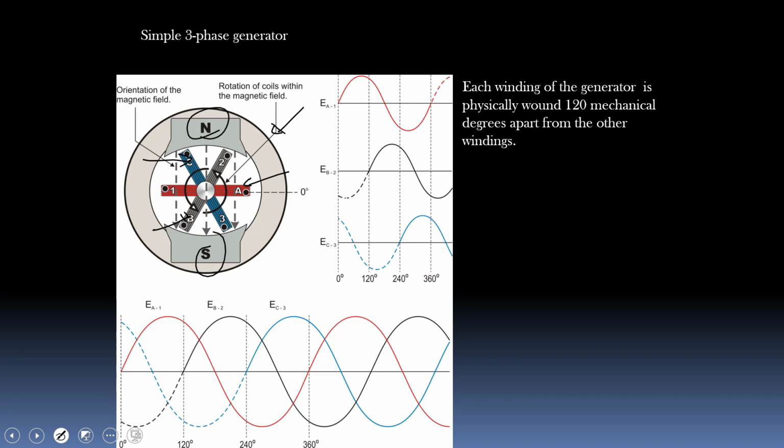On each coil, there's going to be two wires popping out, one end of the wire and the other end of the wire. That's simple. This is a very simplified generator. If we did have a generator like this, those two ends of those wires would come out along the shaft, and they'd come out on something called slip rings. So we'd have a total of 6 slip rings here and carbon brushes riding on that to get this three-phase out. It's not too often that we have generators built like this. Just a very simplistic view so that we can see what's happening.